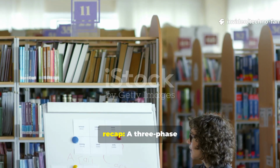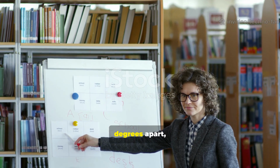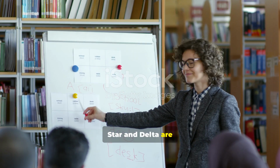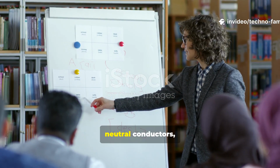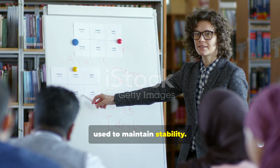Let's quickly recap. A three-phase system consists of three voltages 120 degrees apart, represented easily using phasors. Star and delta are the two major connection types, with different voltage and current relationships. When loads are unbalanced, neutral conductors, delta windings, or transformer arrangements are used to maintain stability.